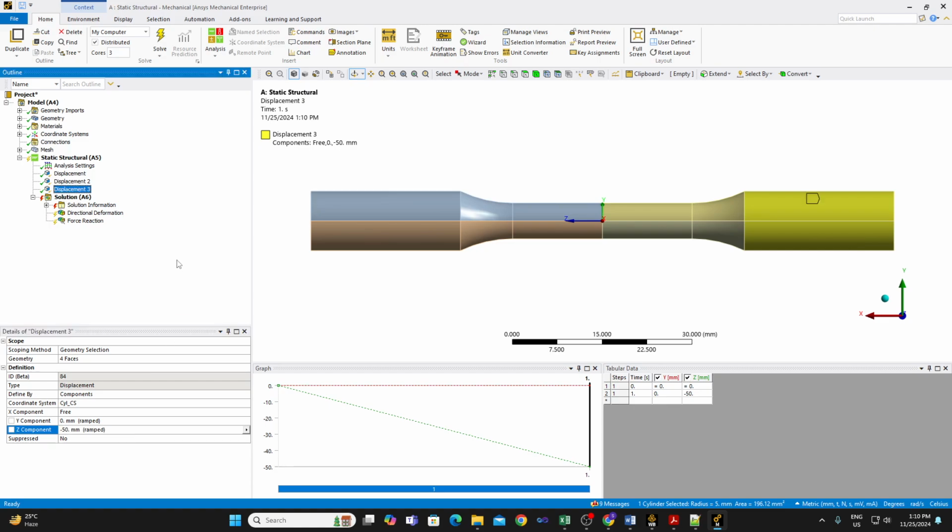Remember, this portion from this line to this line over here, this circular segment, is around 30 millimeters. So this uniform portion is about 30 millimeters. So I have applied an elongation of nearly 2 times that length. Okay, so I'm expecting more than 100% of strain.